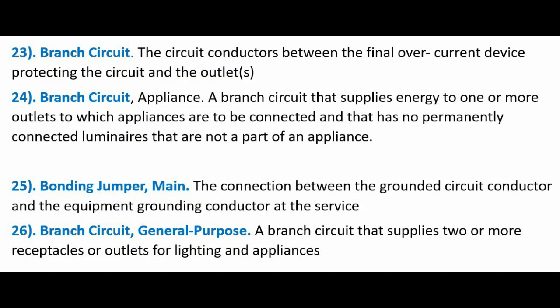23. Branch circuit. The circuit conductors between the final overcurrent device protecting the circuit and the outlet. 24. Branch circuit, appliance. A branch circuit that supplies energy to one or more outlets to which appliances are to be connected and that has no permanently connected luminaires that are not a part of an appliance.